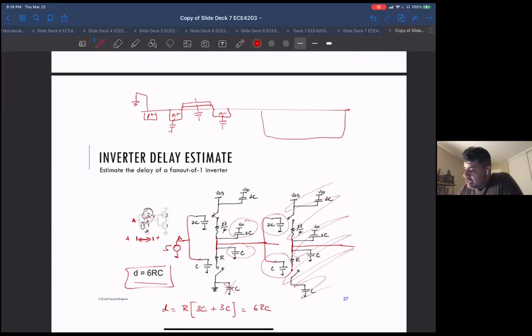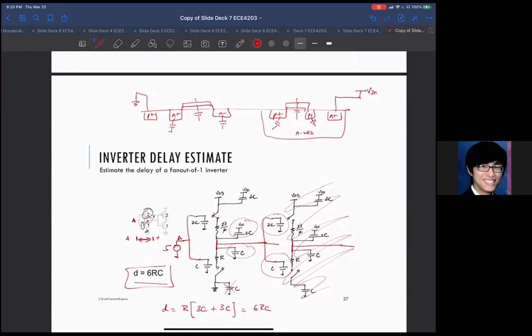And a PMOS is sitting in an N well. This is the P plus, N plus, and so that's connected to VDD, and so these guys are also connected to VDD. So always, essentially, the NMOS capacitors get connected to ground on the other side, and the PMOS capacitors get connected to VDD. It's not almost always, yeah.